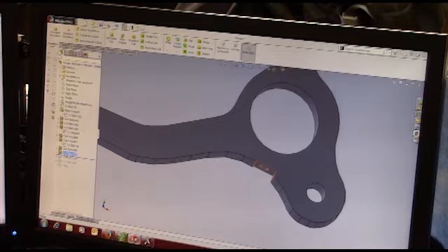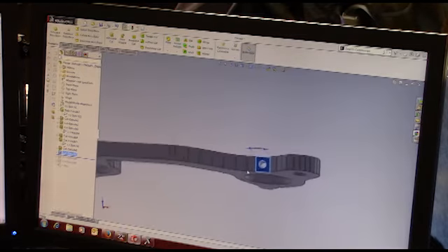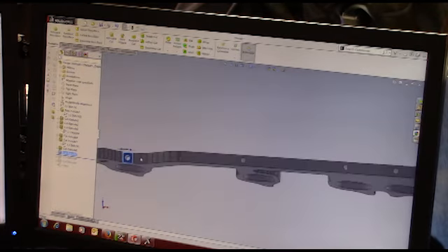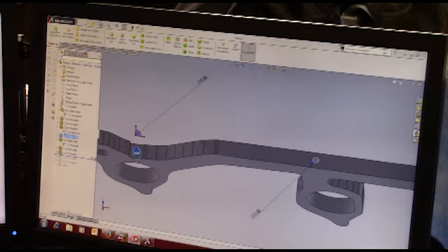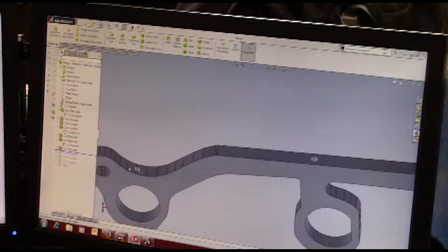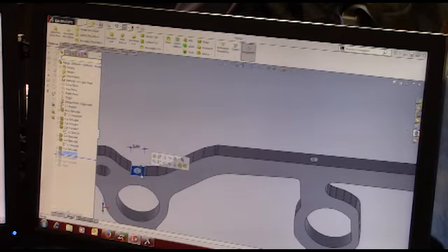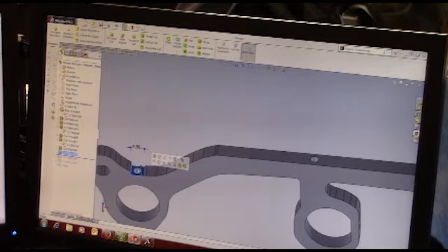Working further down the part, the next thing we had to do was, because when we stand this feature up to put these mounting or these portholes in, this is actually a curved surface. And we really can't machine and drill a hole on a surface that's curved. So we added a little feature here. Again, it's not going to affect the function, where we put a flat on the part to give it some place to drill to start finding its center and actually drilling the hole.